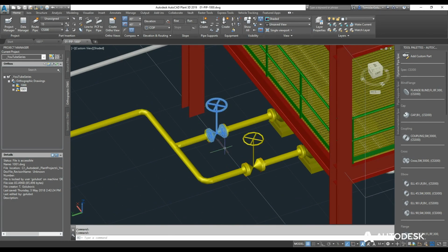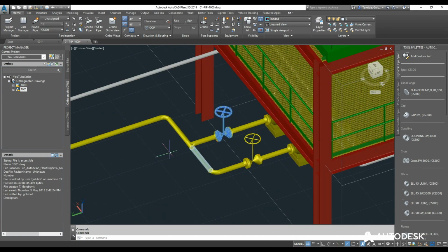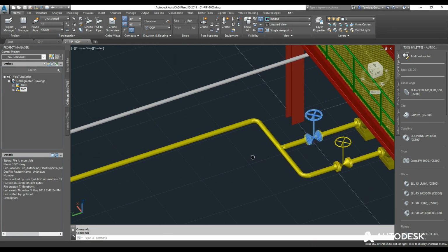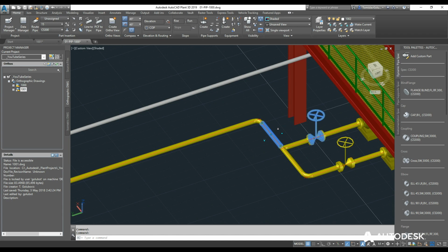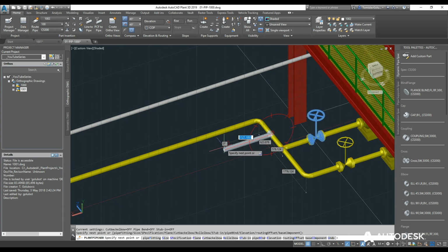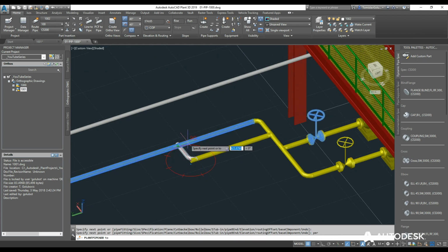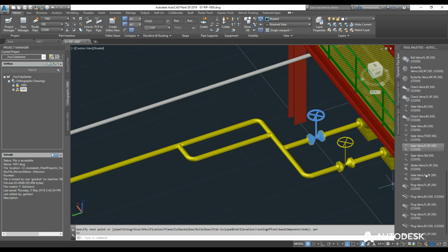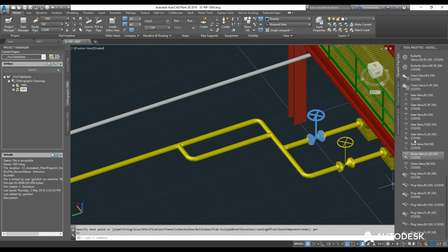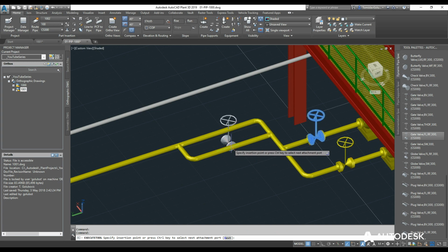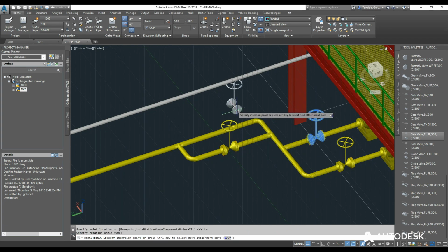So just to show you what happens if something changes. So let's put in a quick little bypass in here. So I'm just going to stick it 2 meters this way and then come across and place it perpendicular into there. And then again, this isn't off for PNID, but let's put in a flanged gate valve. Okay, so I can close that off.